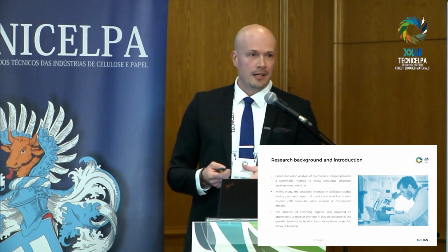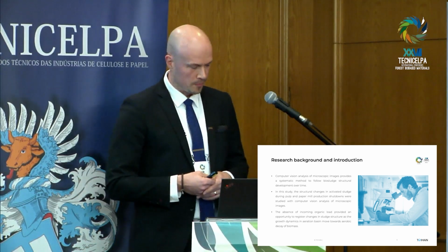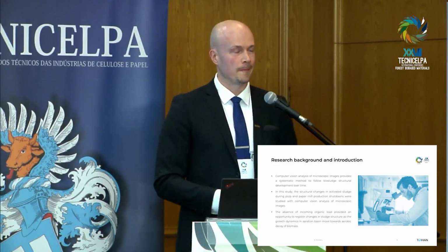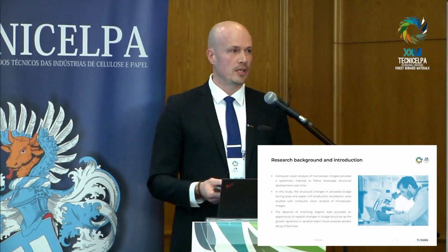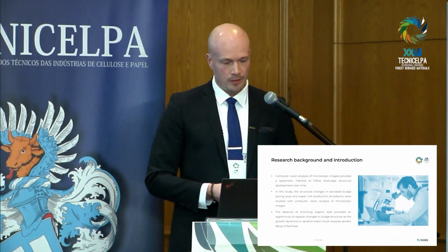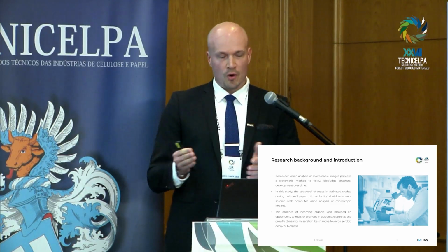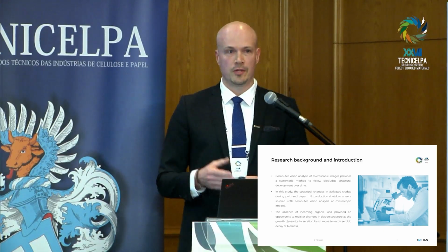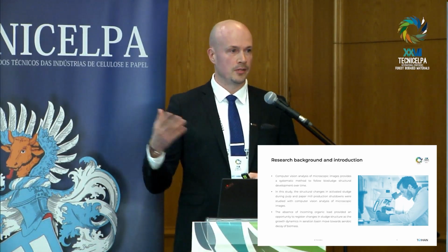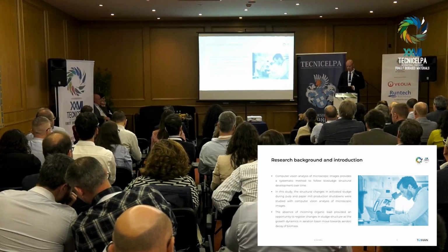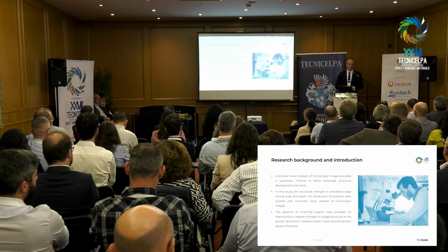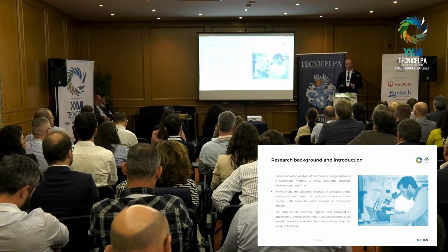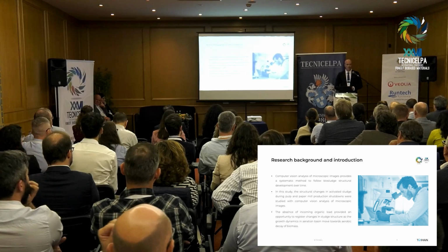The idea of why we want to use computer vision is that we can extract data from those images with a timestamp. So it becomes not only image data, it becomes numeric data with a timestamp. So it can be combined with other process parameters, other variables that contribute to this biosludge generation or formation in the activated sludge process. And the whole idea of wastewater treatment is to convert dissolved material into suspended solids that can be separated from the water.